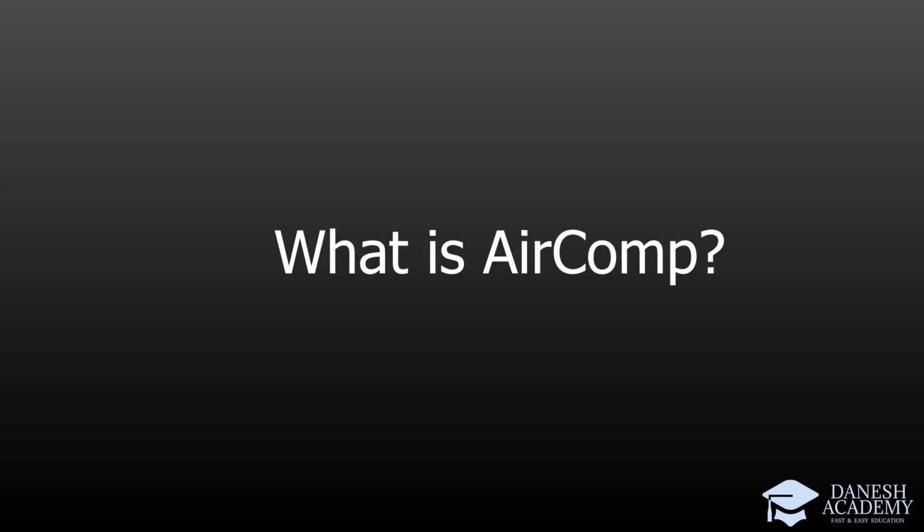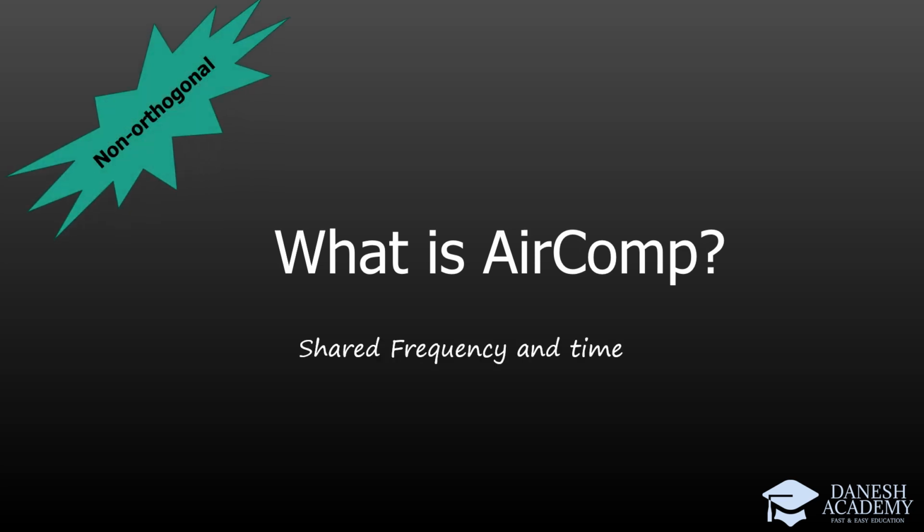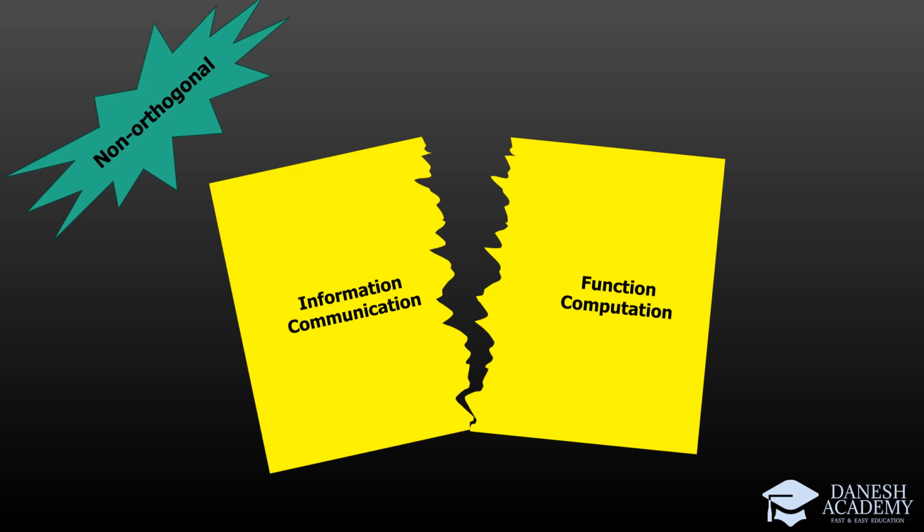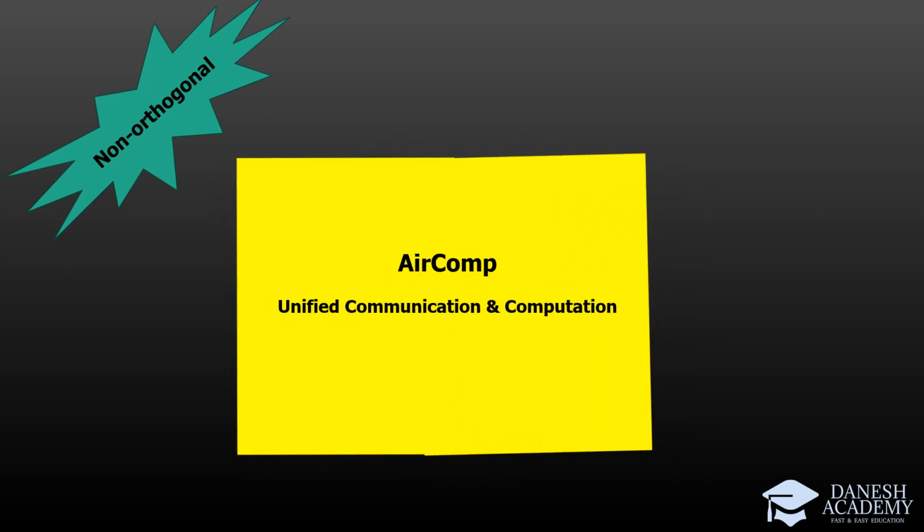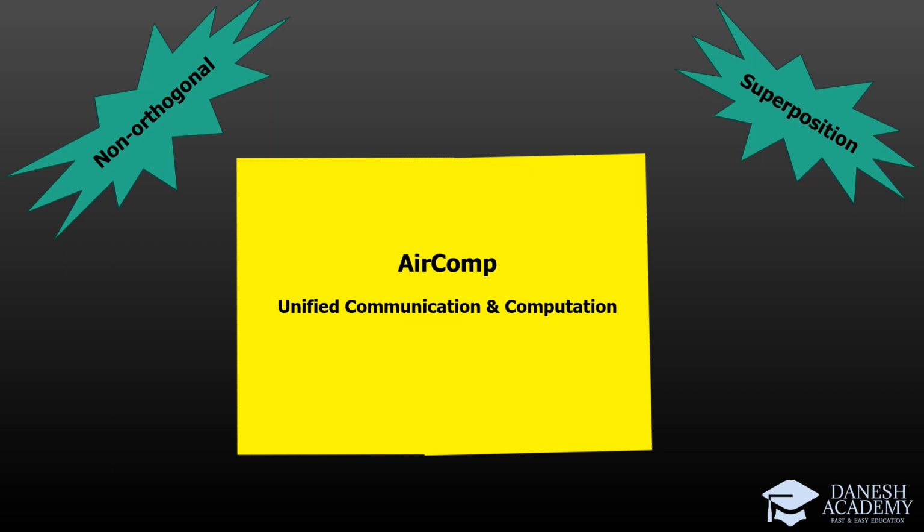Till this moment, an important question still remains: what actually is AirComp? AirComp is a technique in which devices transmit simultaneously over a shared frequency and time resource, similar to non-orthogonal multiple access techniques. However, instead of separating communication and computation, it unifies these two parts by benefiting from the superposition property of wireless channels.